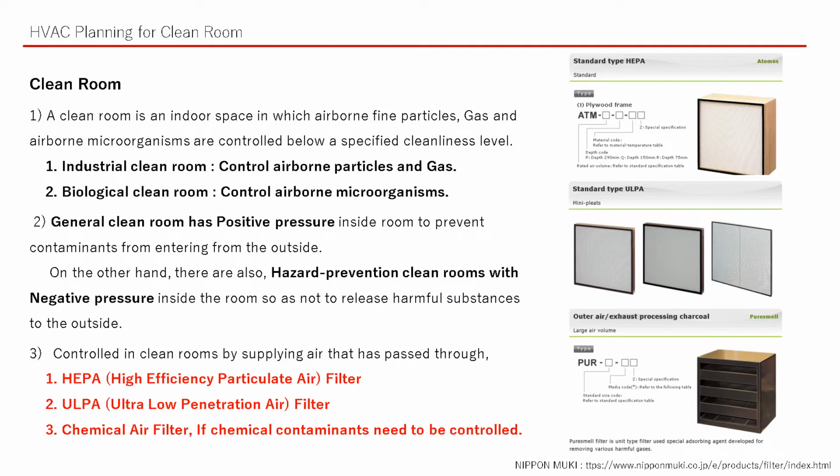Item 3. Cleanliness is controlled in clean rooms by supplying air that has passed through these filters: HEPA filter, high efficiency particulate air filter, ULPA filter, ultra low penetration air filter, and chemical air filter. We can adopt the chemical filter if gas contaminants need to be controlled.